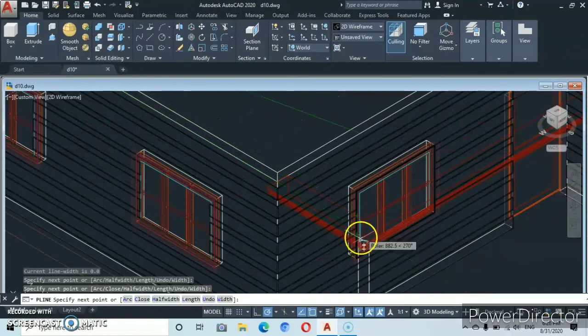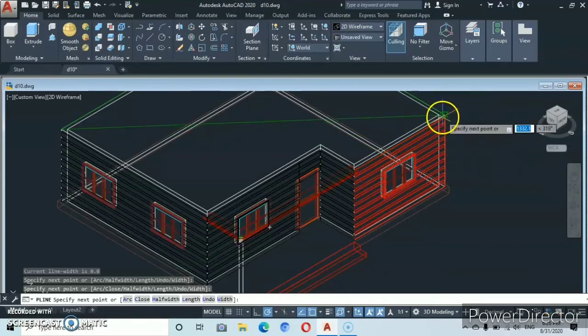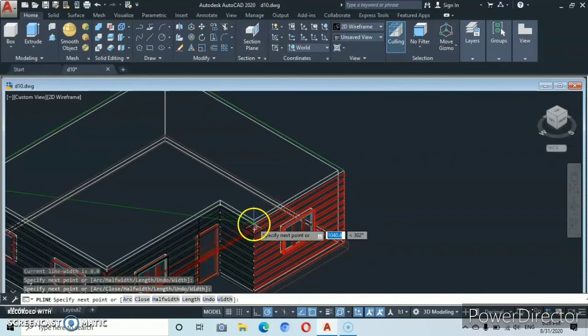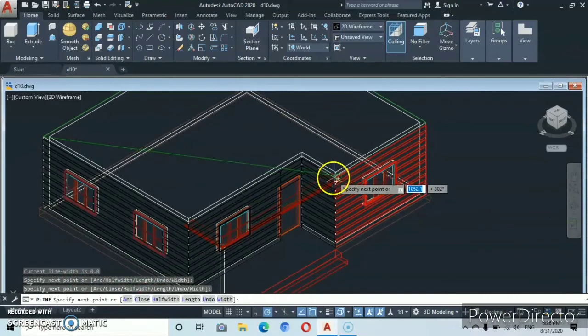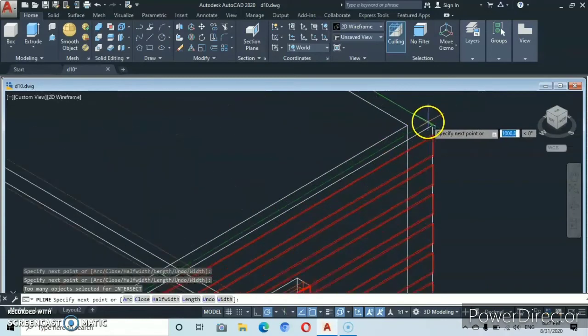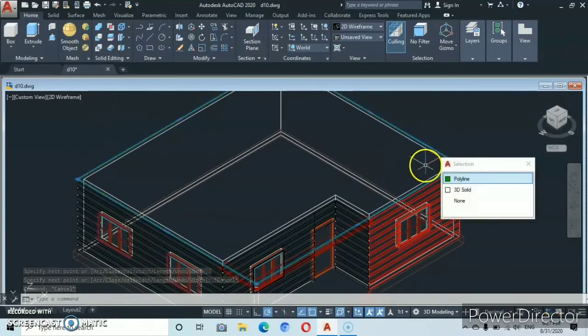There is a beam here, so it's going to be complicated. We don't have an endpoint here, so we have to move right over here to track from this endpoint. Okay, we track from this endpoint. Be careful because we have many different endpoints. Track, follow carefully. We go back, we track, follow carefully. Okay, here we click at intersection. Let's click it here, then we'll move it directly to click at this other endpoint. Good. So here we have our polyline.